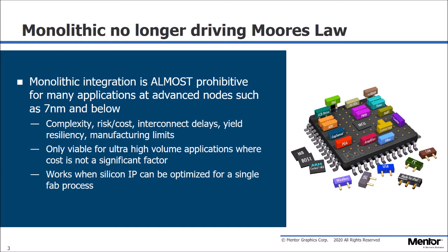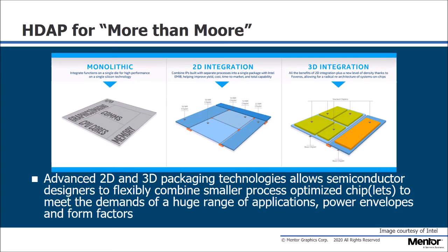Instead of the challenge of integrating functional IP blocks all at the same process node, there's now a trend for disaggregating the once monolithic device into a collection of node-optimized heterogeneous or homogeneous IP chips or chiplets, which are typically interconnected together on some form of high-performance interposer as part of an advanced IC package. Such integration offers a path to enhanced device functionality, faster time to market, and silicon yield resiliency.